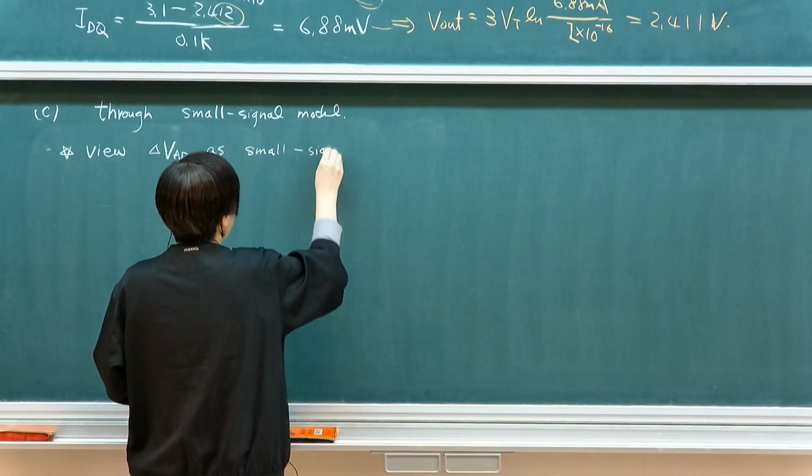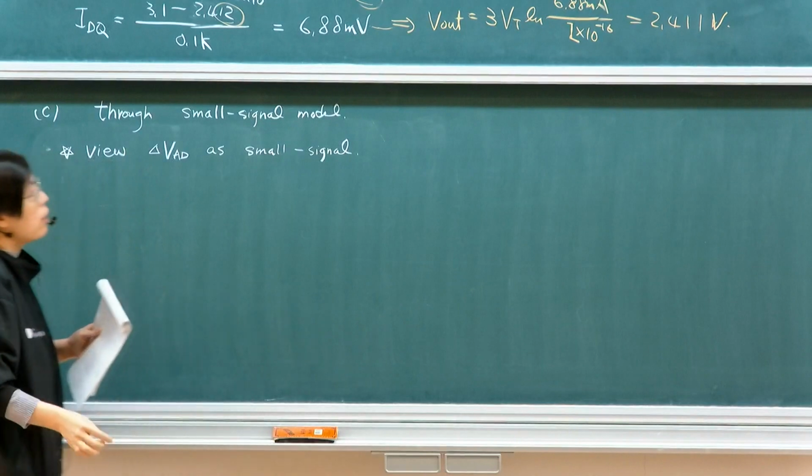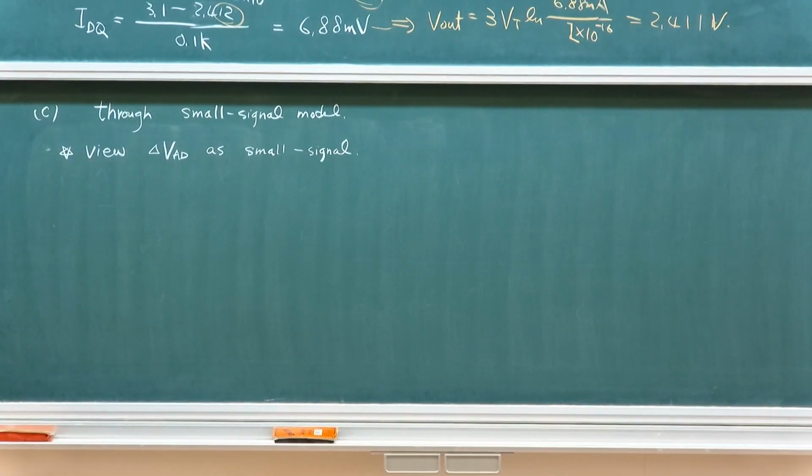And you might have the question that it does not actually fit our small signal approximation assumption. Remember, what is the assumption? What's the small signal approximation assumption? The voltage on the diode, VD over VT, should be smaller than 1, right? But this is 100 millivolt. So does it fit?